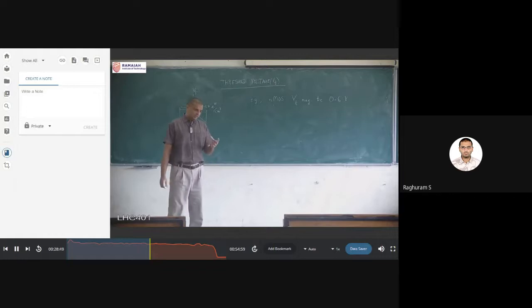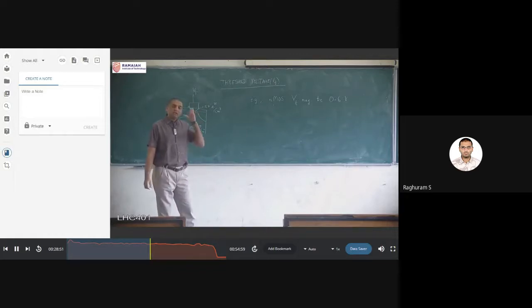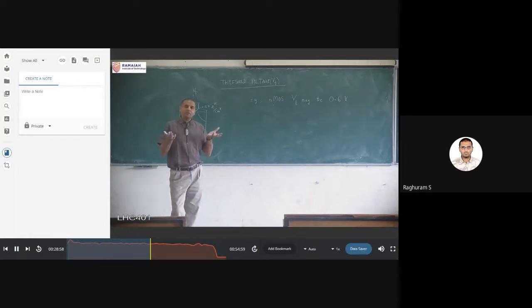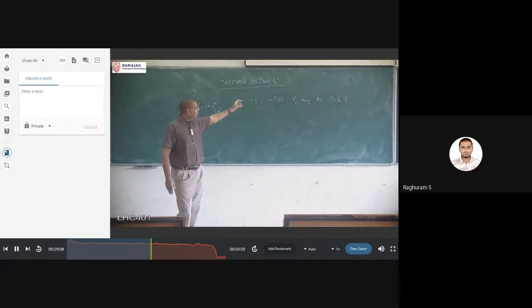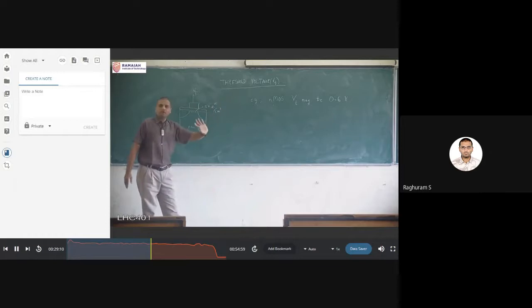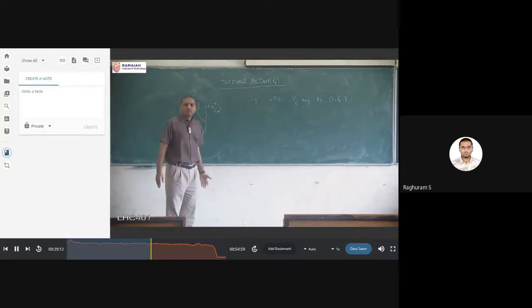But one thing is, for an NMOS transistor, it will be a positive value, because for the NMOS transistor, we looked at the structure, we looked at how to attract electrons. You can never attract electrons with a negative number. It has to be greater than 0. 0.1, 0.2, maybe not enough. It has to be a positive number and significantly large, maybe 0.5, 0.6 volts. So maybe it is 0.6 volts for an NMOS transistor.